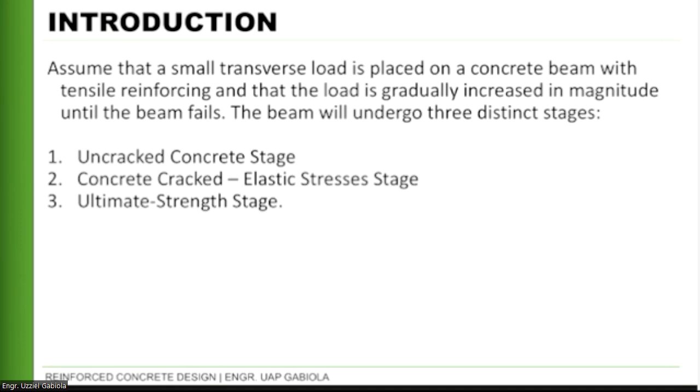Unlike when you reach a certain point, the tension part of our concrete will be neglected already because we assume that it's already cracked, and when it's cracked, it cannot carry any more forces or provide resistance to our loading. Okay, so for today again, we will just focus on the first one, which is the uncracked concrete stage.